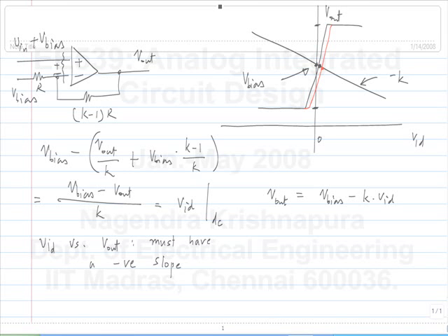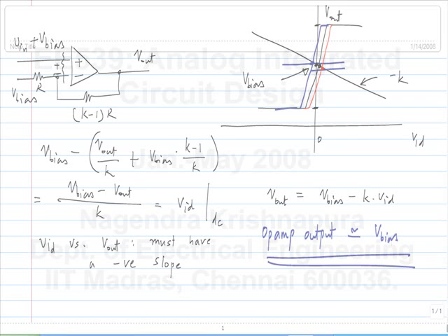So you have to choose a certain bias point for the output, and you have to make sure that your feedback network will give you that characteristic. That is, it will intersect the op-amp characteristics at that bias voltage. Now what happens is, because you have negative feedback, even if I shift the characteristics back and forth a little bit, the actual bias point does not change too much. So any circuit that you make, you have to ensure that this is true, right? Is it okay?